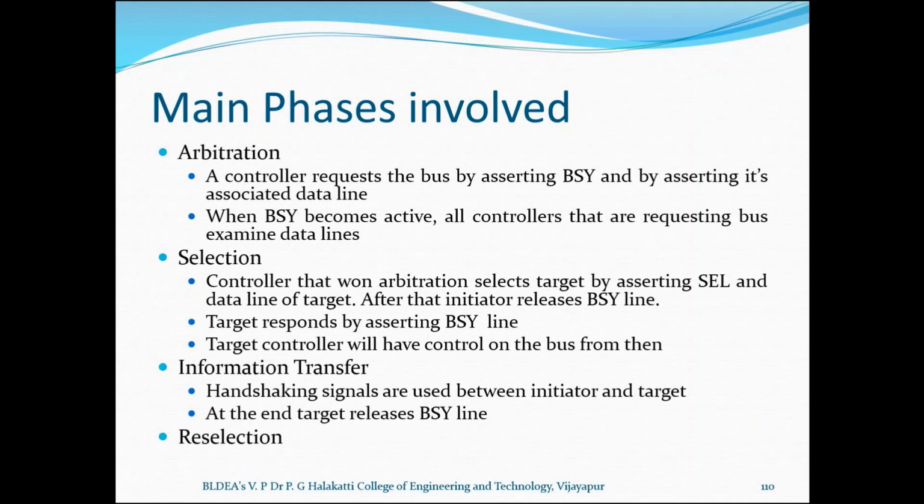So let's summarize once so that we will remember it. The SCSI standard provides the mechanism needed to establish a logical connection and exchange messages between two controllers. The connection requires one initiator and one target controller, because one has to send and another has to receive. The connection can be suspended and re-established at any time.